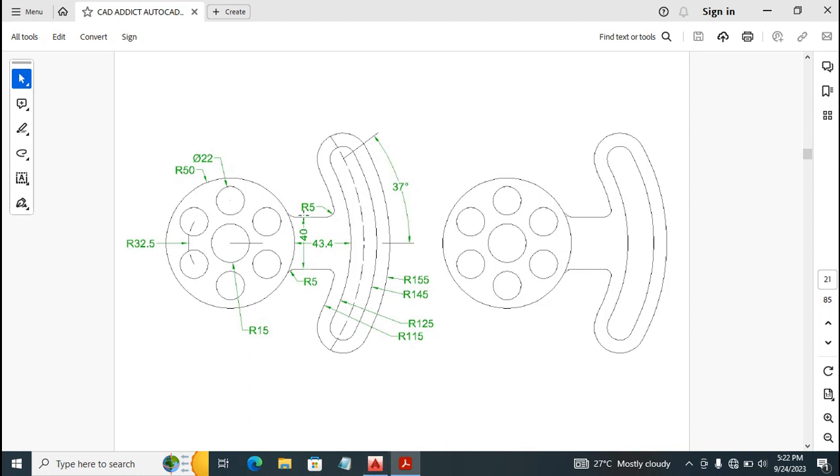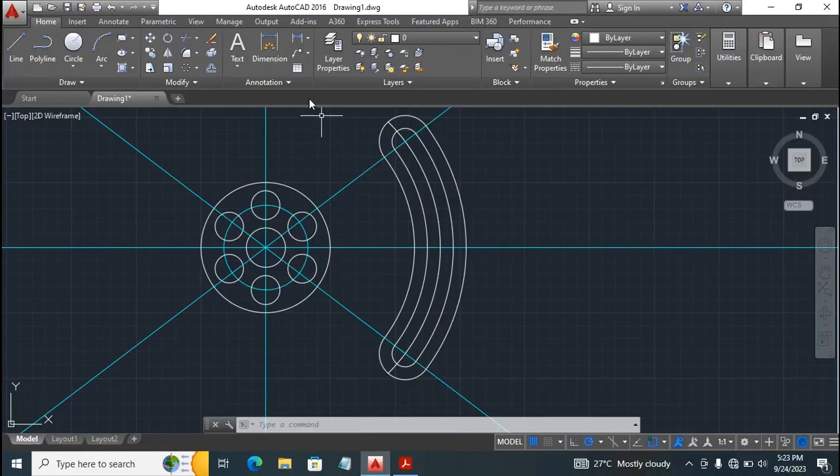So we are going to be offsetting the horizontal construction line on both sides at a distance of 20 millimeters. All right, then we'll draw lines connecting this lever and the cycles using our main line. Then we can later on put in those fillets here at the edge, or at this point of connection. All right, so back to CAD.